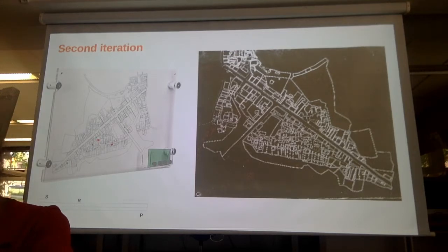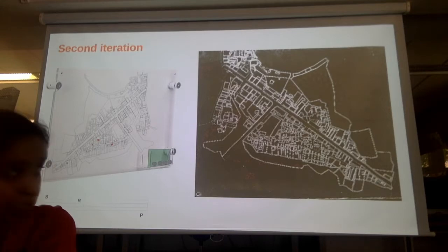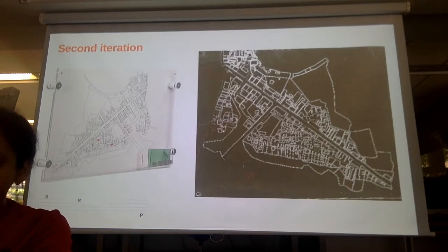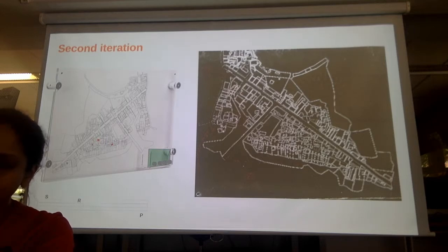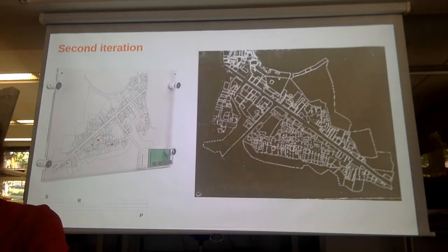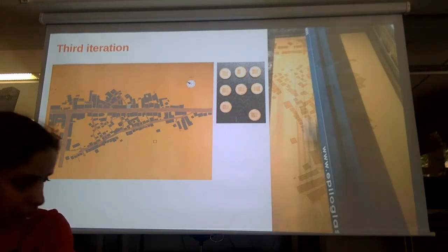So here, what happened was everything actually worked well, and 2 sheets of it were done on the laser cutter and 1 of it was still engraved on the CNC machine. But when you put it all together, the refinement of the drawing does not come about, and the whole purpose of how I wanted the engraving to be seen could not be seen at all. It didn't match because the laser cutter's accuracy did not match the drill's accuracy, so the drawings were of different accuracy.